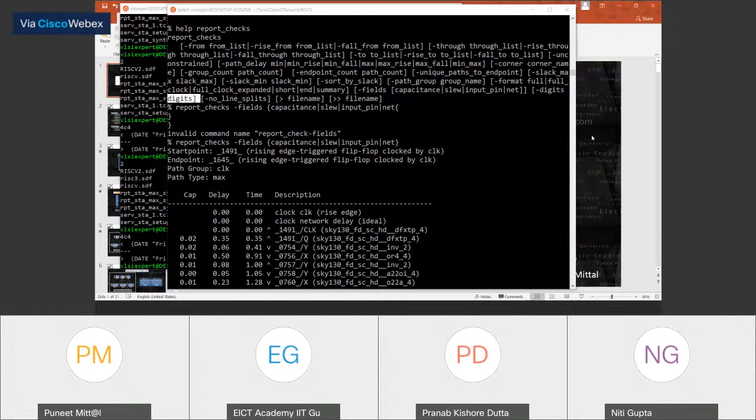Okay, so Surya, you were asking what OR4, O22A, O21, etc. indicate. Basically, it's the nomenclature. It's basically the name of the cell. This is the complete name of the cell. Now, what type of cell it is? From the functionality point of view, I recommend you just go to the .lib file and check it. I can write any name in place of this. I can also write Surya.